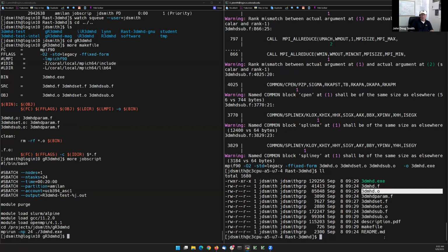The other thing is you may go in and decide, hey, I don't need to dump my variables as often. I may give you a simulation and say, dump the variables every 2 iterations. But I also say in there, this is a variable you can change. So you're going to need to look and go, you know what, I'm willing to risk it and dump only every 10, or every 100. Or maybe the model is super small and you think, I can run this pretty quickly, I don't need to dump my variables every iteration.